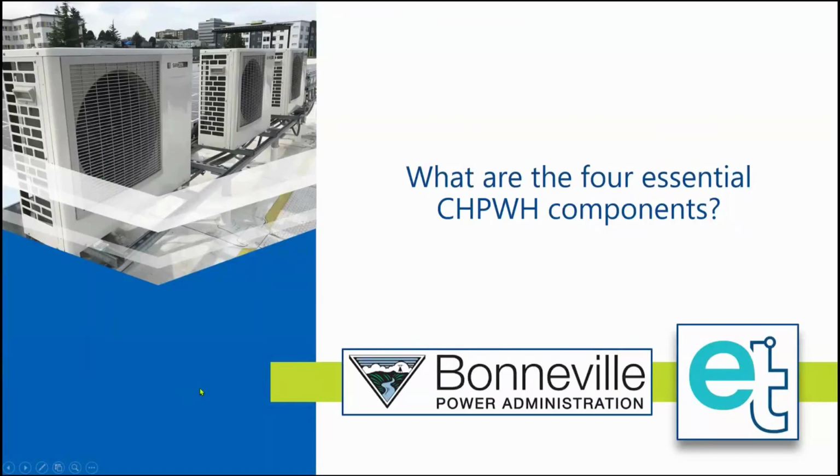I can read to you the other entries in here. We have one that says unclear cost-benefit analysis or an ROI-NPV story of heat pump water heaters. Great. We have a couple more. Could you clarify that the R134 does not work well below 32 degrees? That's an easy one, yes. And then comparable energy use savings between standard CO2 and 134A systems.